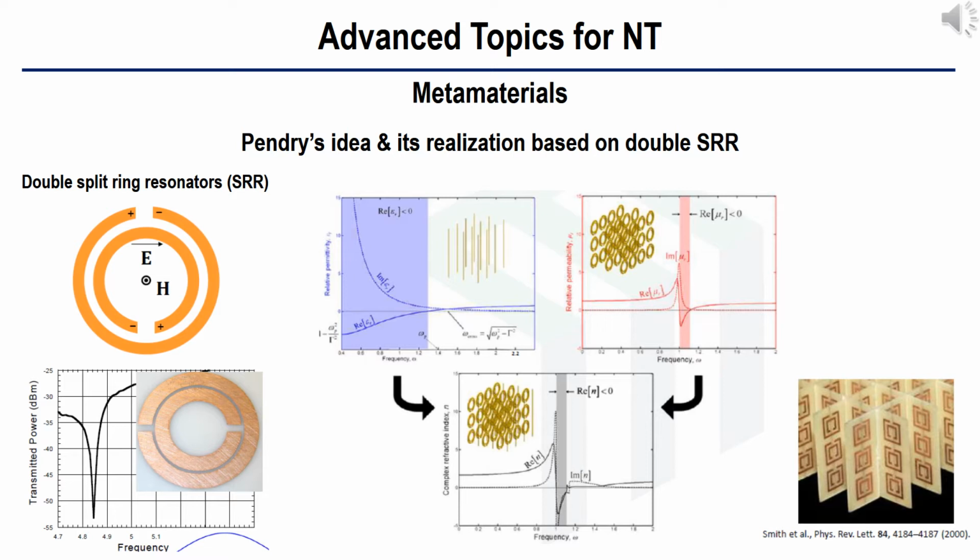In conventional materials, the dielectric response derives from the constituent atoms. As discussed, negative or positive electric permittivity is possible over a broad spectral range. However, natural materials with a resonant magnetic permeability don't exist above a few terahertz. For example, ferromagnetic resonance in iron at microwave frequencies or antiferromagnetic resonance in MnF2 at 2 terahertz.